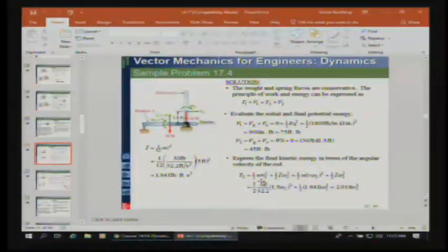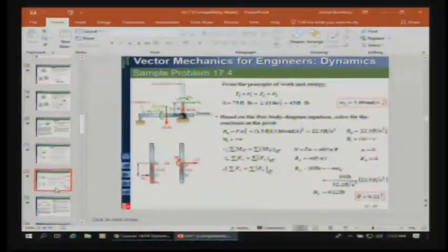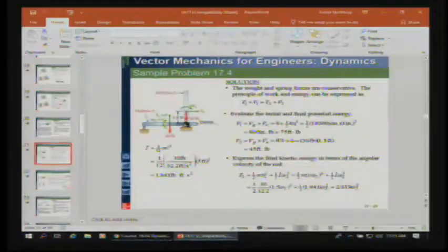Once again, we have mv squared. We also have the I bar omega squared term for situation 2. And when we get to the vertical position, we could probably make some assumptions about the velocity center. Not really. We can't really do that. In other words, we can't really assume that it's going to be 0 because it could be coming back through. It's not like a projectile. There's no reason to expect that it's going to reach a 0 velocity at that point.